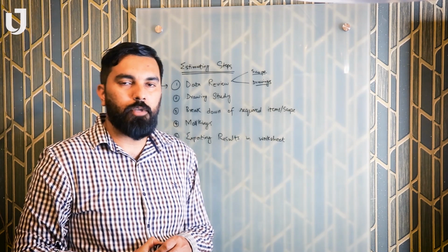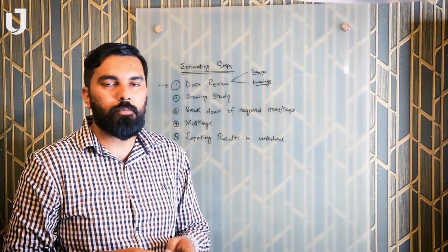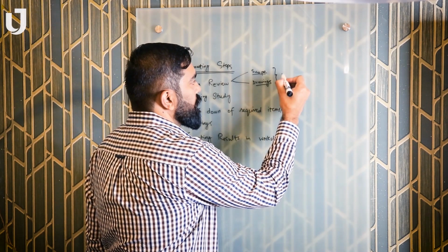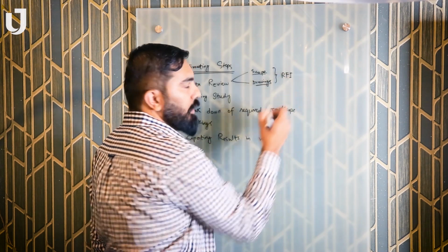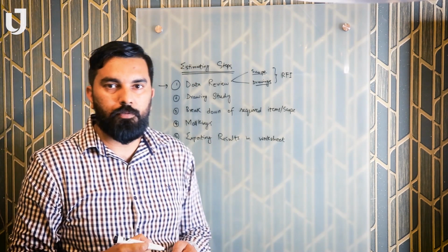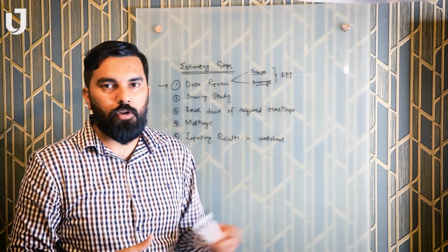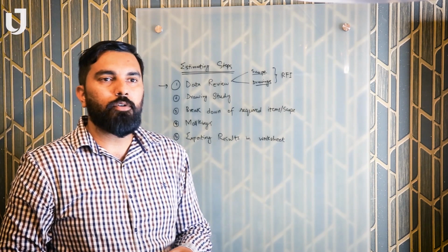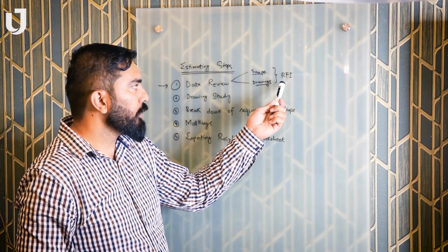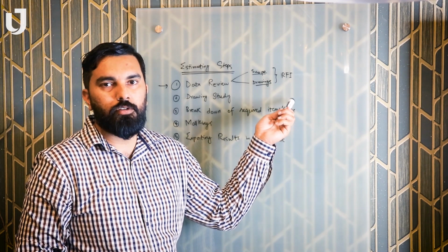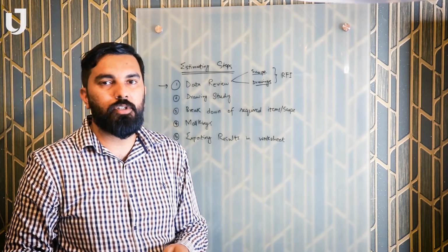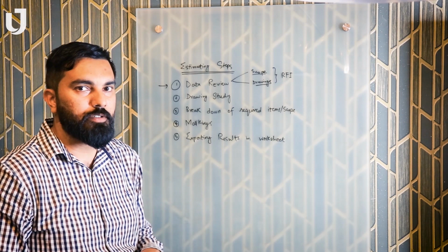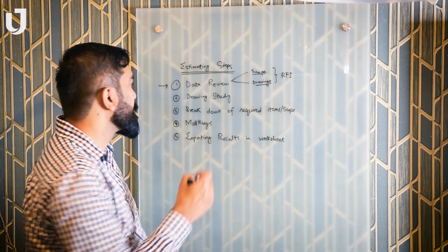Sometimes we do have the table of contents, we can re-verify if any detail or any page is missing. So we immediately have to put in RFIs, requests for information, if any data related to our quantification is missing in the drawings. And it's a pretty normal thing. Most of the cases, maybe 40 to 50% of drawings are lacking details. So sometimes we have the capability to send RFIs, and sometimes we have to make engineering judgments based on our experience. I'm going to let you know when the time comes about the decisions that we have to make if the details are missing.